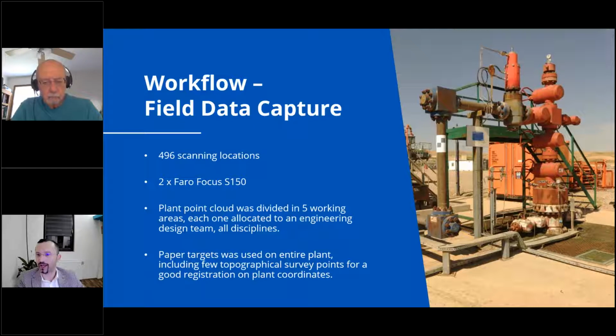We received the point cloud in our office. Because the client didn't want magnetic targets placed on the site, we used paper targets all over these areas for a proper registration of the scanning.